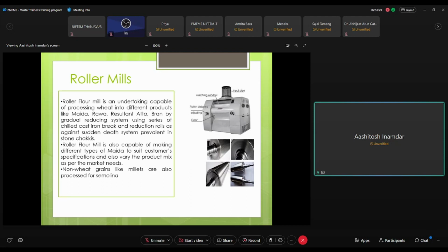Cleaning section machinery can normally be put in a higher capacity, right? Suppose you have a plan of 100 tons per day of grinding capacity, and your cleaning machineries will have the capacity to finish all the cleaning in say only 8 to 10 hours, right? So that you get clean grain for grinding throughout the day, right? And suppose expansion happens, you just run the cleaning section for 8 to 10 hours and stop it.